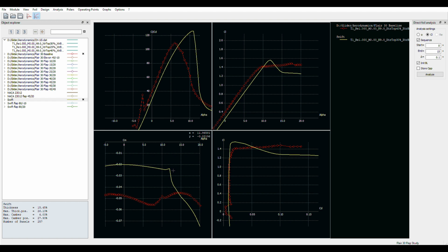You're not chasing the pitch all over the place. It stays well behaved, and you can pull the nose up, and you don't have to worry about jockeying the controls around to try to trim the aircraft. And remember, we had reports from the Flair pilot that crashed. He was having difficulties trimming the aircraft as he slowed it up towards stall, and that its stall is down around 10 degrees.